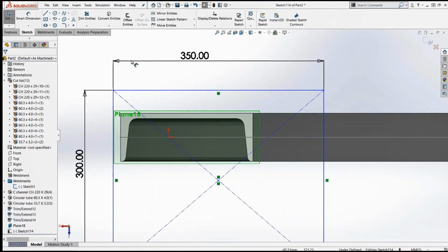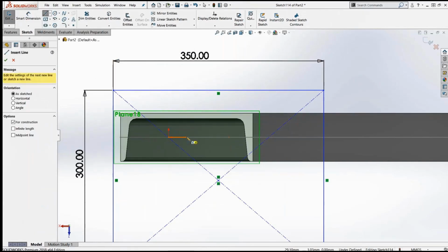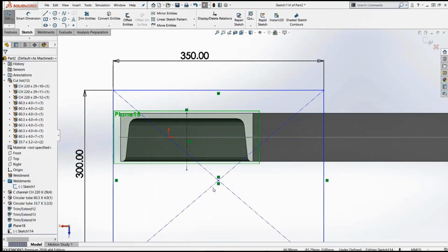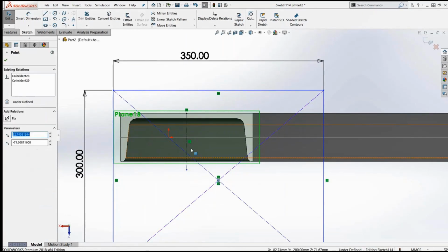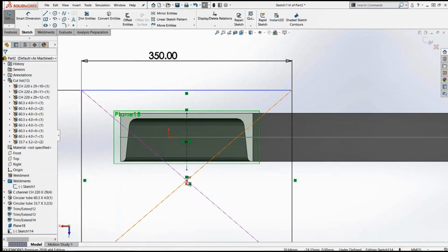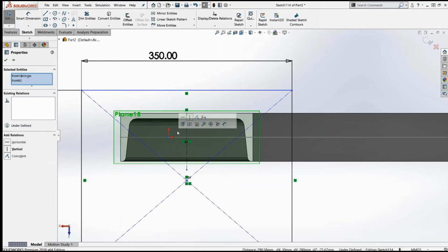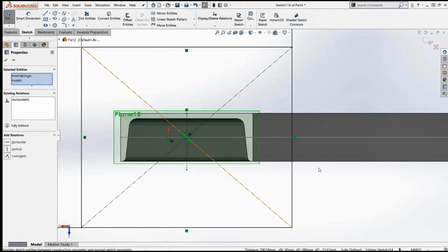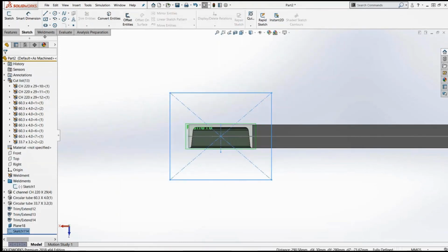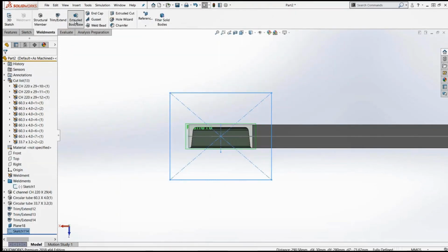And you'll see that once we complete this extrusion, it's actually going to interfere with our structural member. So we're going to have to trim the structural member which makes up the main frame of the staircase. We're going to have to trim that to fit perfectly onto the base plate. So again, as you've already seen, the Trim Extend tool can be used to trim structural members, and that's the tool that we intend to use for this operation.